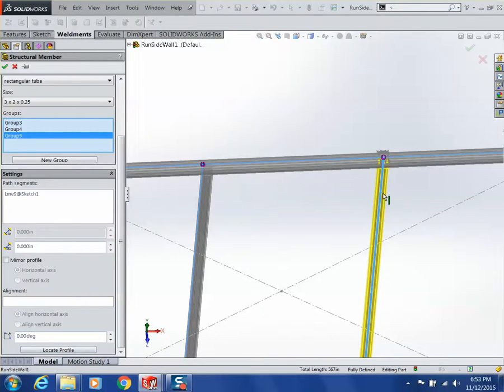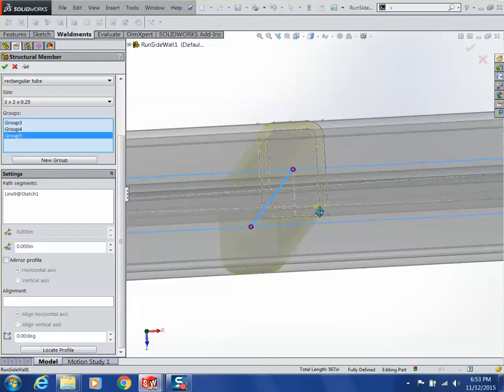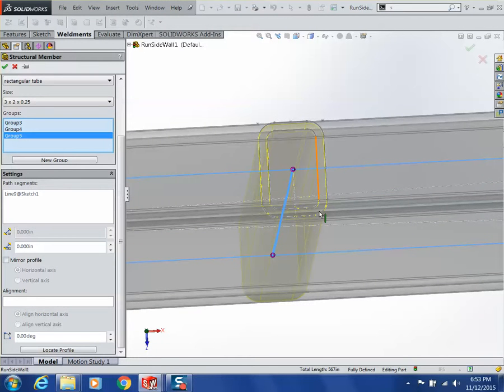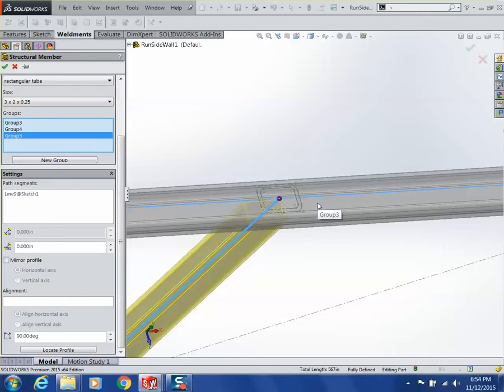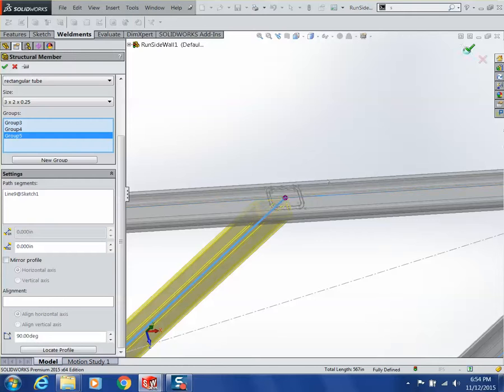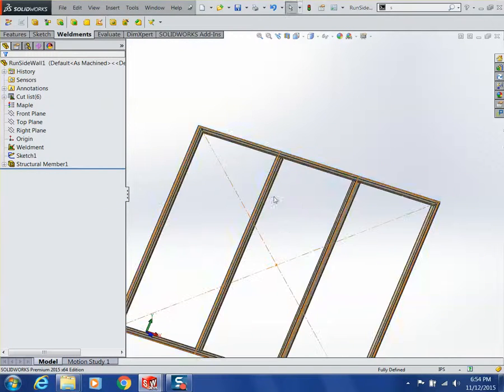Let's throw in a curveball. Let's take this one, and I want to have this one turn 90 degrees from everything else, because that's the other thing you run into when you don't have a symmetrical extrusion. When you don't have a square extrusion, can you flip this thing? There's an option for that right here. I can take this and turn just this one 90 degrees. So you have options to be able to go through. This is where groups are going to be your friends. Anything that you want to behave the same way, group when you walk through them. Okay, so once all of that fun stuff is done, you hit OK, and it's done. There it is.